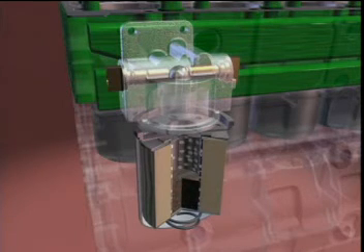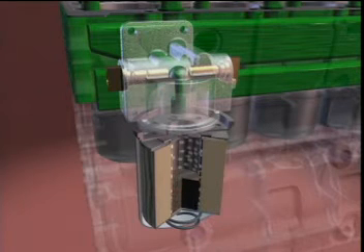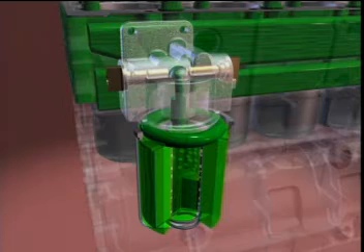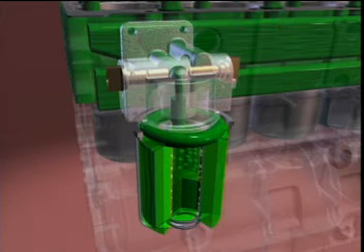The higher pressure coolant in the lower manifold pushes the coolant through the filter. After passing through the filter, the coolant returns to the lower pressure upper manifold. The orifices in the cylinder head gasket provide the pressure differential in the upper and lower manifold to force flow through the filter.